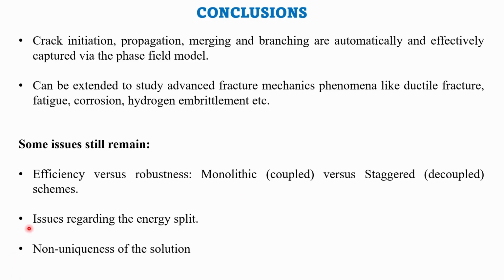We have some lingering issues regarding energy split, as I explained in the previous slide, and non-uniqueness of the solution. Non-uniqueness of the solution comes when you have a lot of micro cracks. So you will find that for the same configuration, if you do two different simulations, there might be chances that you will not get the same crack patterns in the two simulations. So non-uniqueness always comes, and we have methods to deal with it, but I'm not getting into them right now.